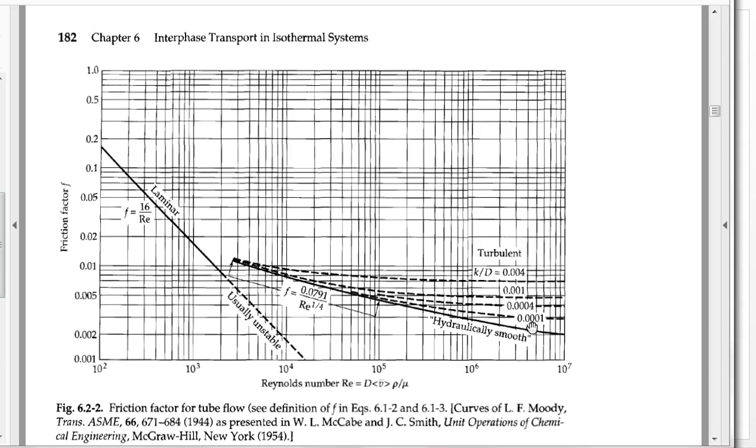And this roughness introduces additional friction as it interacts with the fluid. Essentially, the more rough the wall is, the more area there actually is with all the little nooks and crannies and crevices where the fluid contacts a solid. And so there's more fluid in contact with a solid, a greater surface area due to the roughness, and this creates additional drag or additional stress that we find manifested in a higher value of the friction factor.